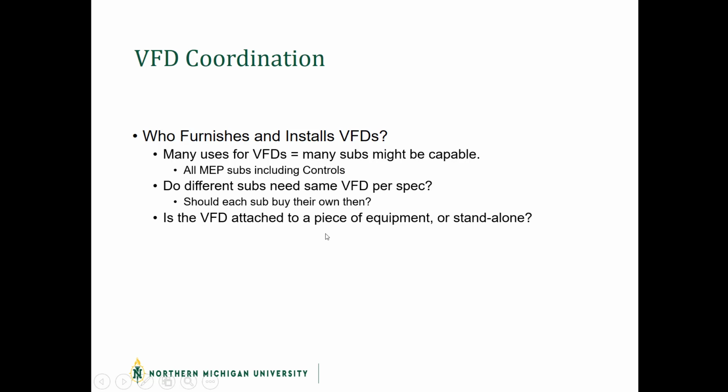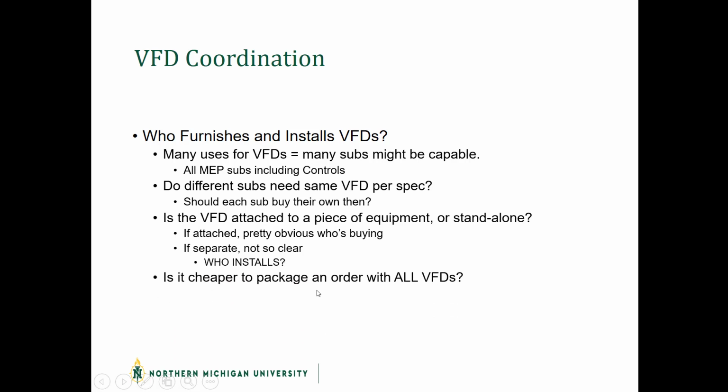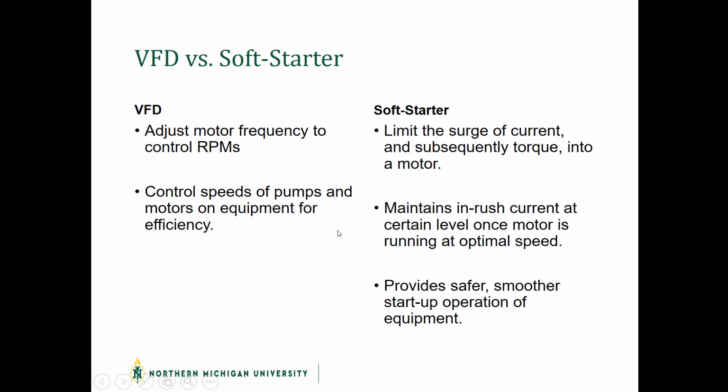Sometimes they're right connected to a piece of equipment. Your air handling unit might have its own VFD right on it. So in that case, it's kind of a no-brainer. The VFD is coming with that AHU, so your mechanical company is going to get it, right? So that's kind of just going through that whole thing. Understanding that that's a kind of a big deal. They're expensive. They help a lot with efficiency and controlling your building properly. So a lot of coordination challenges tend to come with VFDs, so just be aware of that.